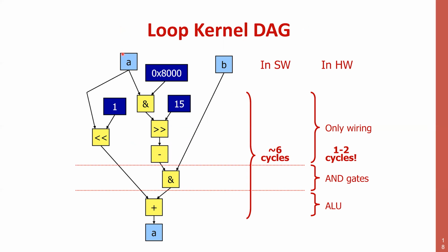I didn't use the fact that this was a piece of a multiplier, right? I ignored it. I just noticed that there are operations that, if I try to do it, simplify. In fact, if you give this VHDL literally of this computation to Vivado or to Synopsys Design Compiler or to any other logic synthesizer, the fact that this is only wiring is going to be found out completely automatically without you doing anything.